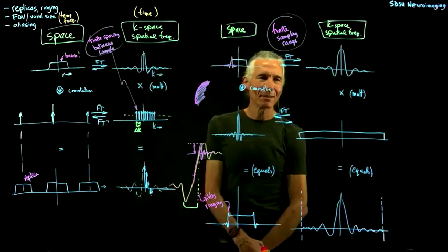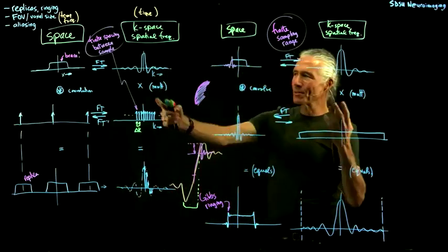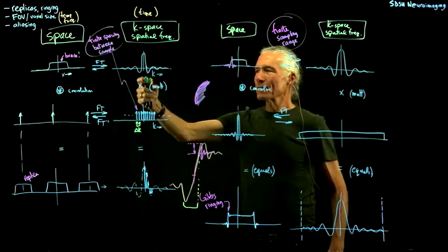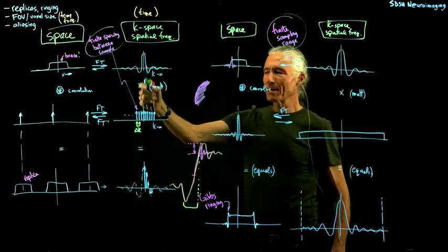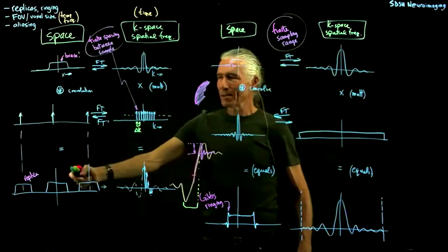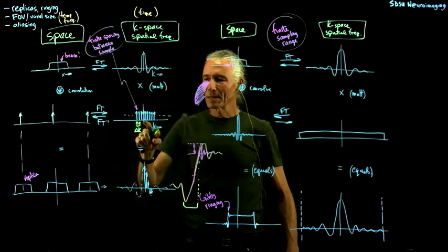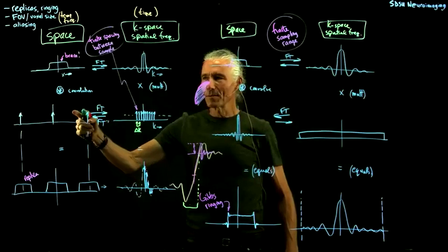So everybody okay on that? It's all sincs. We just use the sinc in two different ways. Here we've got something that looks like a sinc in K-space, and we sampled it, and that caused the replicas because of the relationship between what spikes look like when you Fourier transform them.